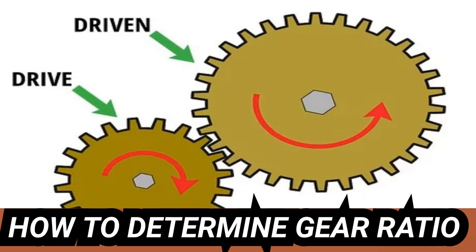Question: How do I determine my gear ratio in my gearbox? Community answer: If you cannot see the gears, you can mark the shaft and the start point on the gearbox and count the number of times it revolves when you spin the other shaft one full rotation.